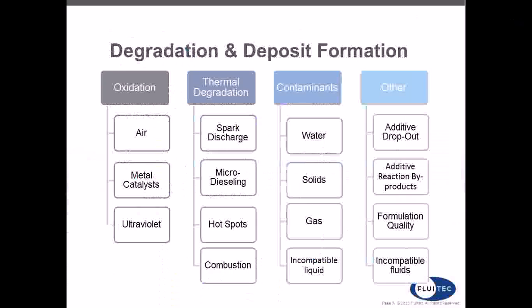When the system is down during an outage, components are opened up, and you have the opportunity to get into a system. If you find any kind of funky looking deposits or types of varnishes, don't just clean it off. Take some photographic evidence of it, capture a piece of it, put it in a bag, and I'd highly encourage you to spend a little bit of money to get it analyzed. It's a unique opportunity to provide some much deeper insight as to what's actually happening in your lube system when it's operating.